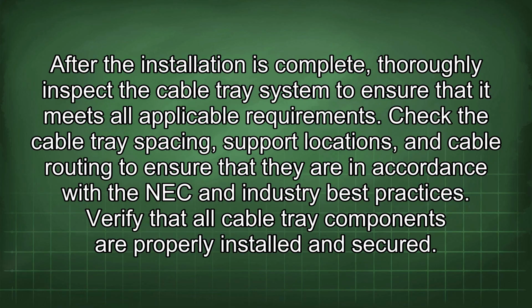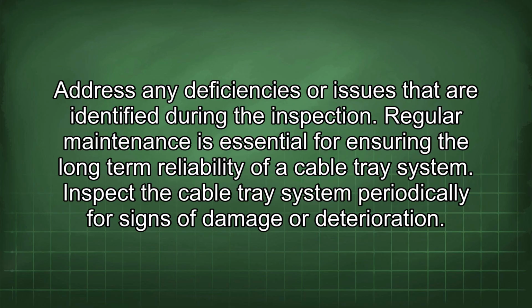Check the cable tray spacing, support locations, and cable routing to ensure that they are in accordance with the NEC and industry best practices. Verify that all cable tray components are properly installed and secured. Address any deficiencies or issues that are identified during the inspection.